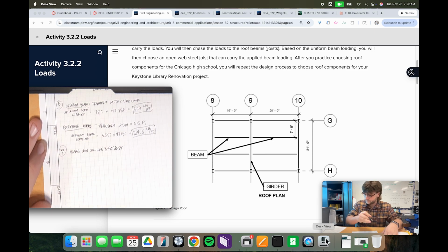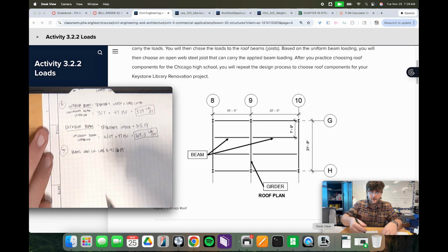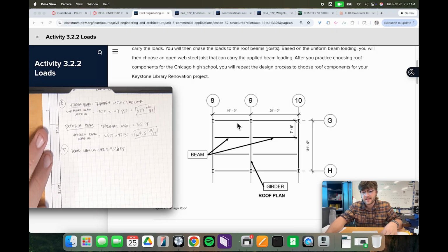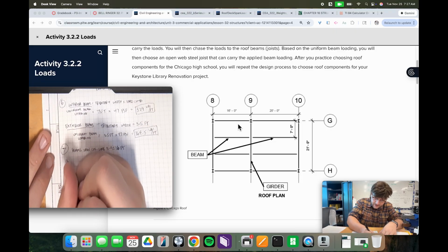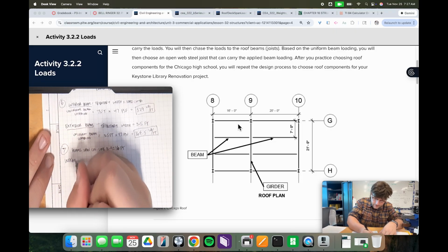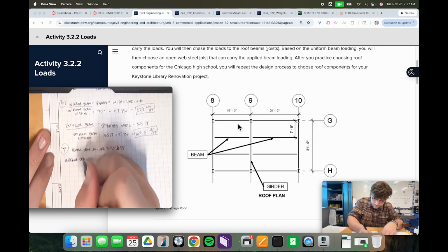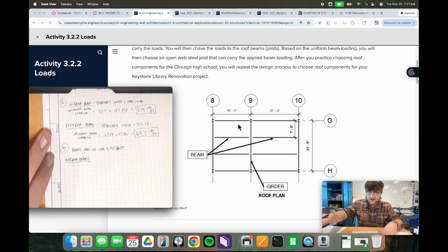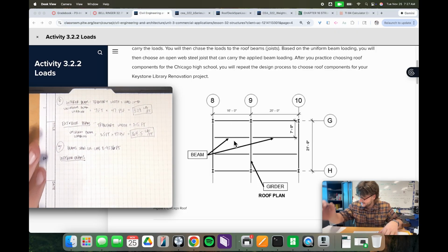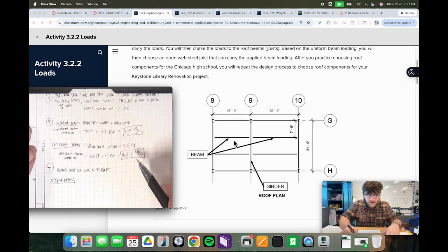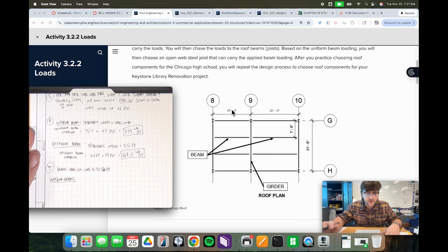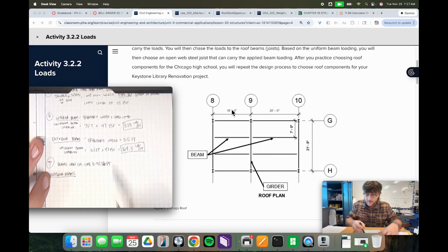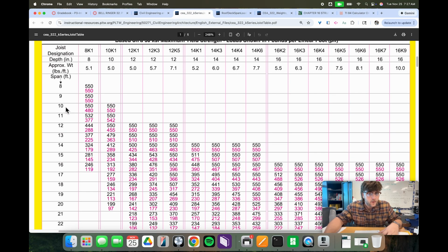That's equal to 16 feet. Now, what we can look at are going to be the interior beams as well as the exterior beams for this. So let's go ahead and go to the interior beams. For these interior beams, on the inside here, we do have that load of 329, right? For our exterior beams, it's a bit lighter of a load. So for these interior beams, we want to look for 329, and keep in mind our span here is 16 feet. So we can go down to 16 feet.